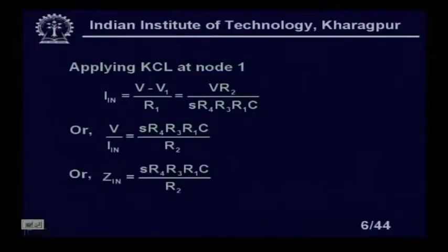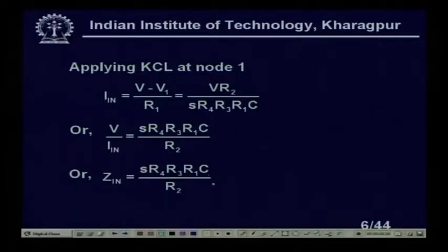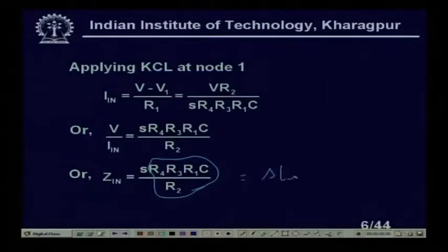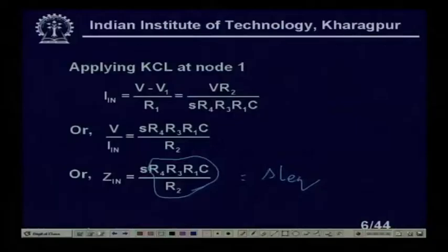Now, you see this entire thing I can write as an equivalent inductance, LEQ. So, we can see interestingly, using one single capacitor, I can simulate inductance in the circuits. I have used one capacitor and some resistors, so I am actually simulating the inductance in the circuits, right. So, it has a tremendous impact in signal processing, in instrumentation at least.